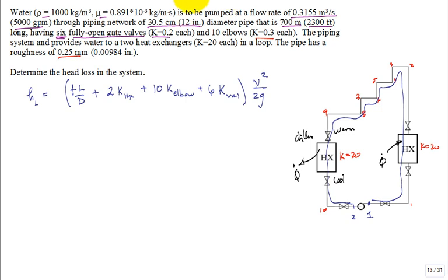Got to get the friction factor. So how do you calculate the friction factor? Convert the volumetric flow rate. Yeah, so we basically need to get a Reynolds number over on the side, and then we get the relative roughness, and then we can get the friction factor.